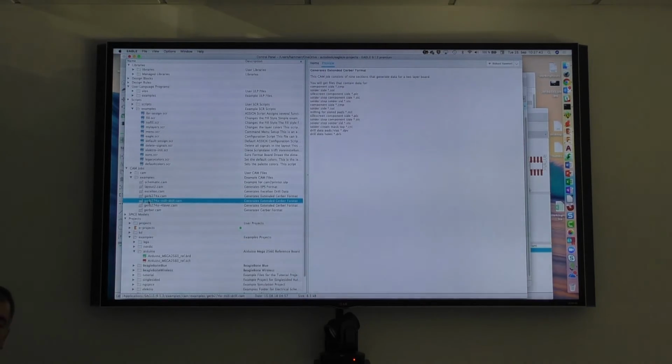We want to have this, what's the keyword here? I don't know, design to manufacturing or something like this. This should be one click and then I get the files. That's already possible maybe, but there also is some improvement needed, because nobody wants to take care of which layer and what do I want here. I need solder stop, silks, and solder paste, milling data, glue there, this, that. That's something the designer doesn't want to take care of. This should be done automatically, and that's the way we want to go.